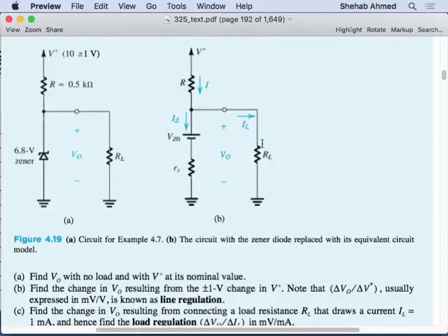Now I add a load. Current here will decrease, which means that my output voltage will be equal to VZ0 plus R Zener times the current. This drop will decrease. At some point, you are drawing more current than what's possible to go through here.